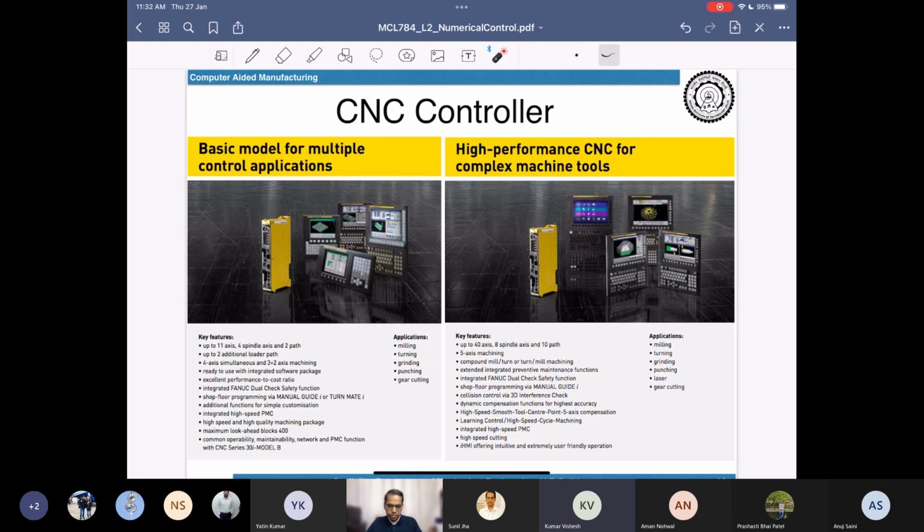So these controllers are very different from each other for every organization. Like Siemens has a numeric controller, and Fanuc is there. But if you see the difference in the controllers, the language is almost the same. The part programming syntax is defined by international standards, so everybody has to follow those instructions. The only difference you will find is that more and more cycles are there. They are trying to combine multiple functions into groups, so these are the additional capabilities.